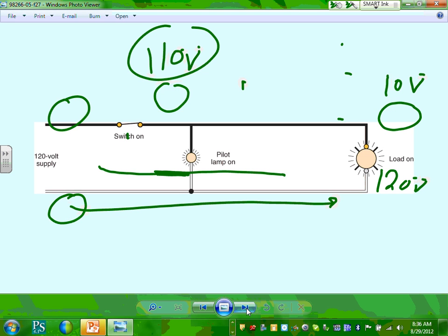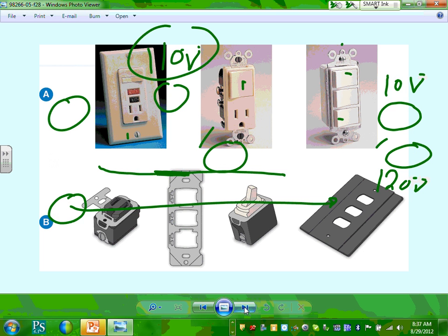So this one is the opposite. This one goes on when the lamp is on, when the load is on. Some people use it, guys, if you have a lighting fixture in the attic and you have the switch here and you can't see if the lighting fixture is on or off, what you do is when you turn it on, a little light here comes on. That will tell you the light in the attic is on. Okay, everybody's okay with that one? Indicating devices. Cool, but look, the switch turned both of them on at the same time and both of them off at the same time.